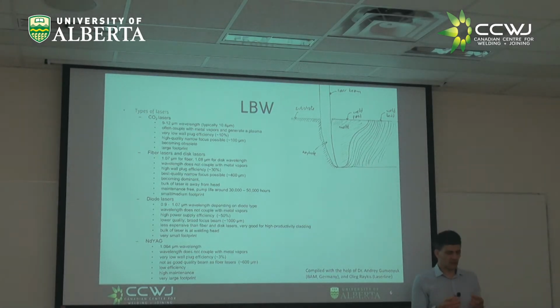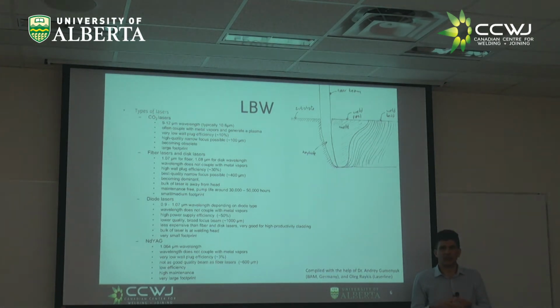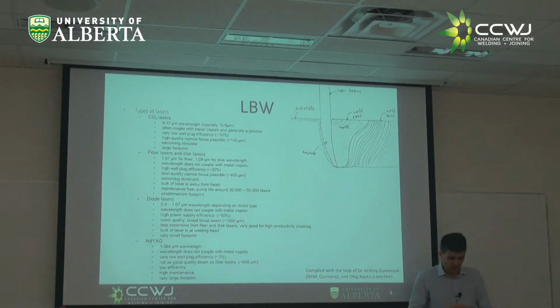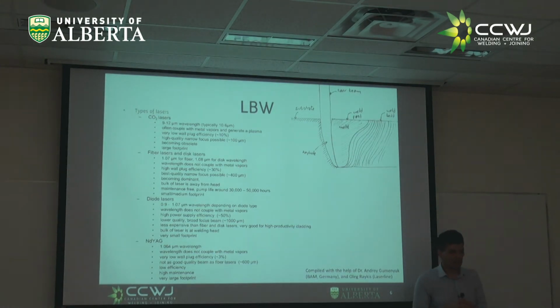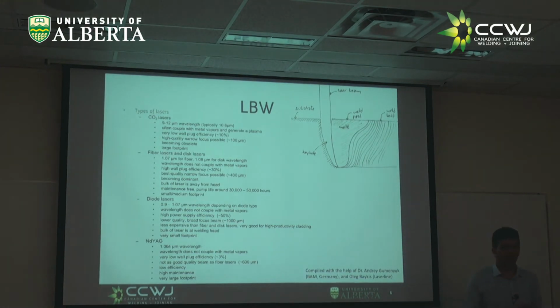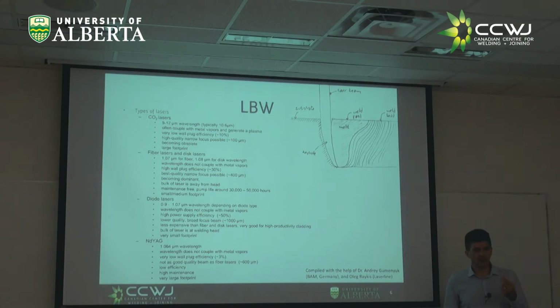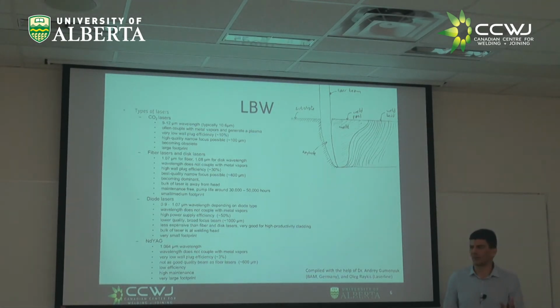But there is a limitation because your heat source, the original diode or the laser pump, has a finite size, and you'll never be able to make it smaller than that. That minimum size is what is going to control your power density, and that's going to limit you. If the power density is not high enough, you cannot do keyhole welding, for example.